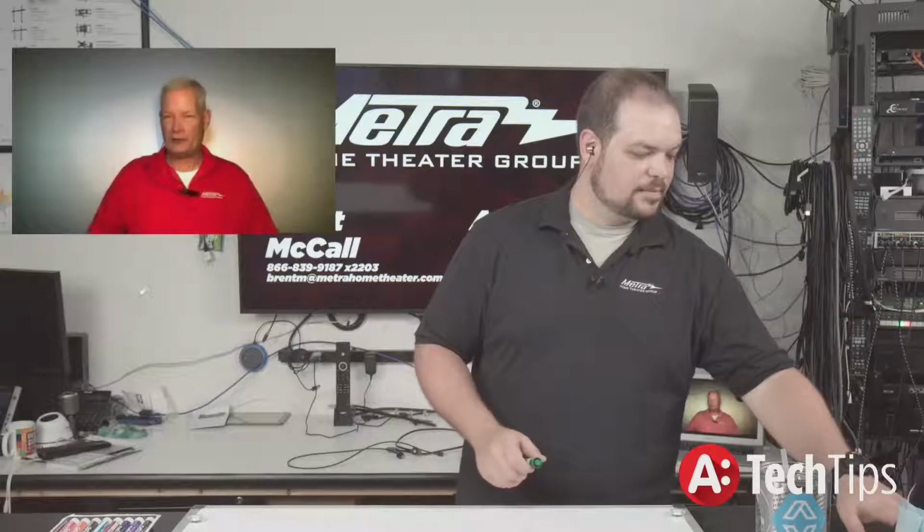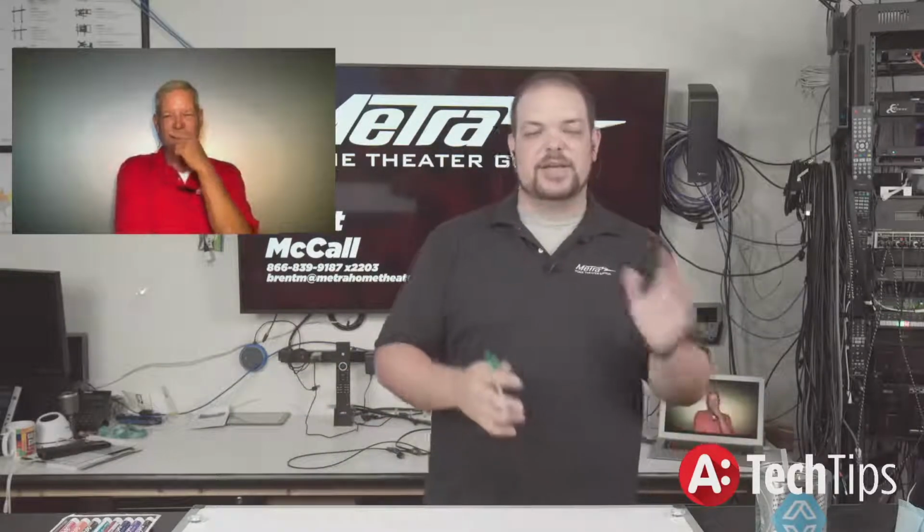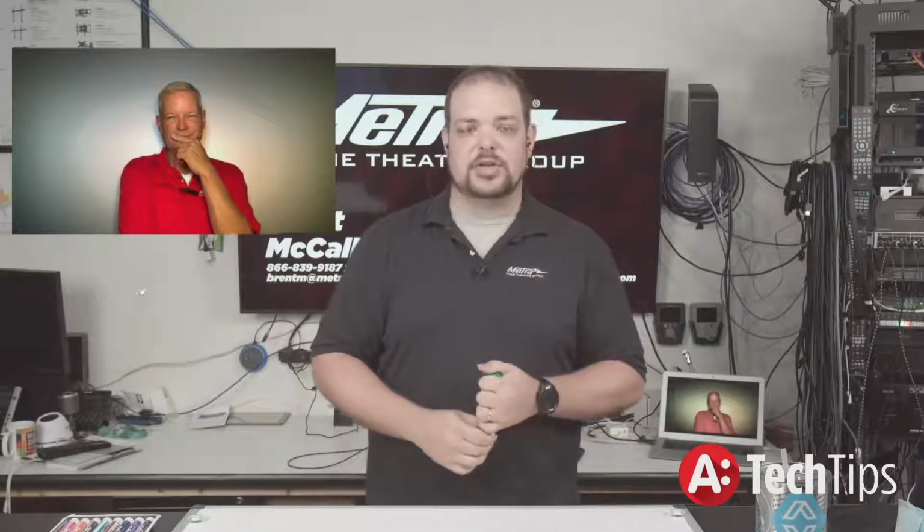We honestly hoped, and I still ultimately do, that we can get a 4K broadcast chip, but it's not there yet. So now we're going back in time, but looking at a very advanced way of doing it because, like Brent's saying, we're still stuck at 1080p currently. There's still technically an SDI connection where you could get up to a 12 or 18 gig connection, but 12.5, and it doesn't support HDR. It doesn't support HDCP 2.2. Actually, it didn't support any HDCP. It just kind of skipped it.